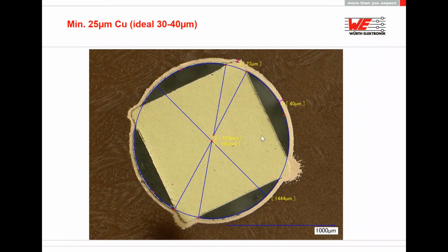The only disadvantage is if you press too far into the FR4 material, you could generate cracks, and cracks are not allowed according to the standard. But in case of functional question, it still would work without any limitations. You can see the cracks mostly in the cross sections like here, but from a practical point of view, you will not see any issues.